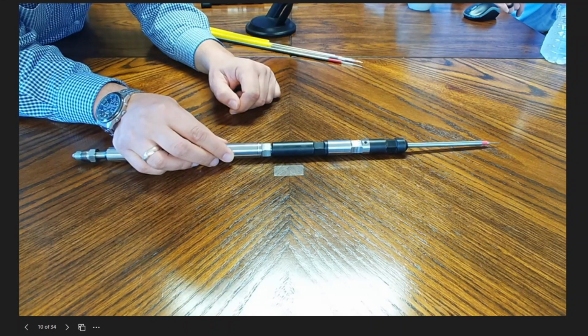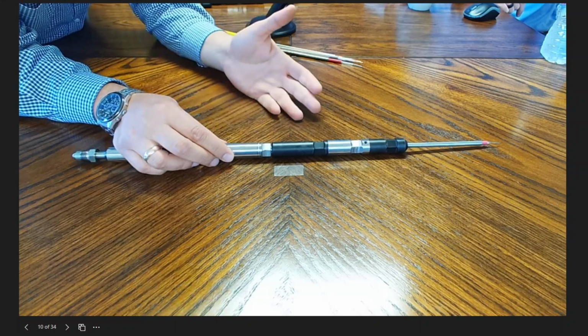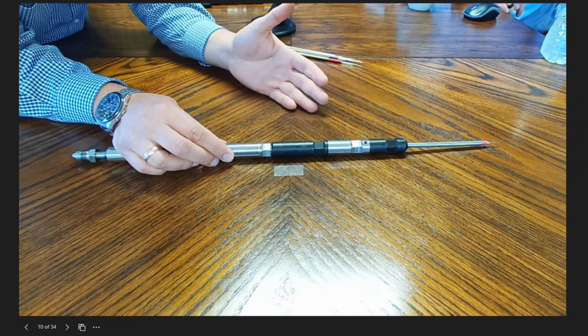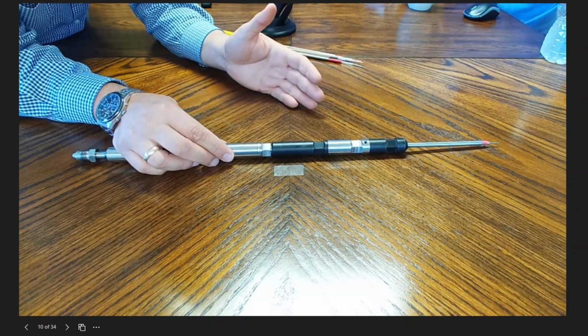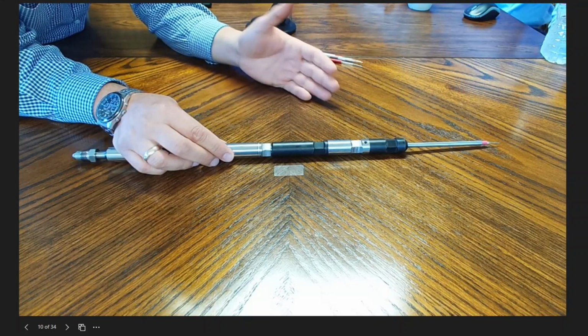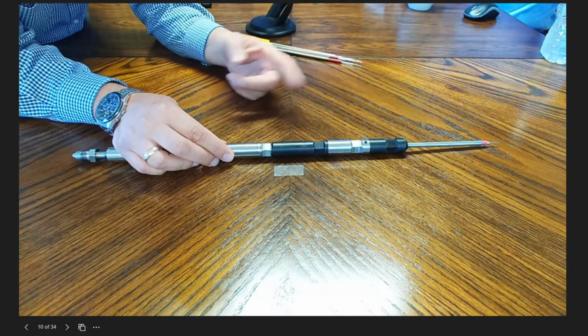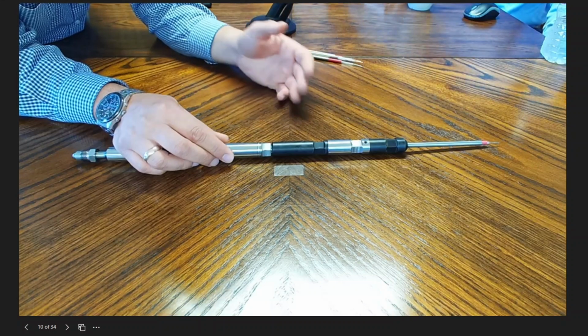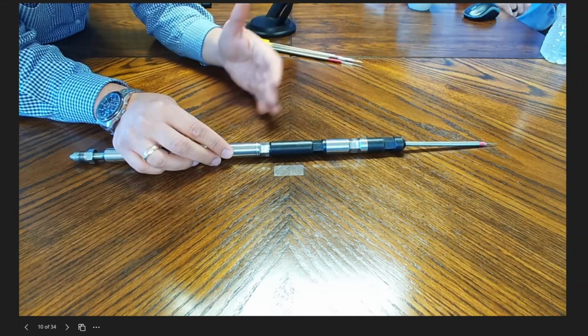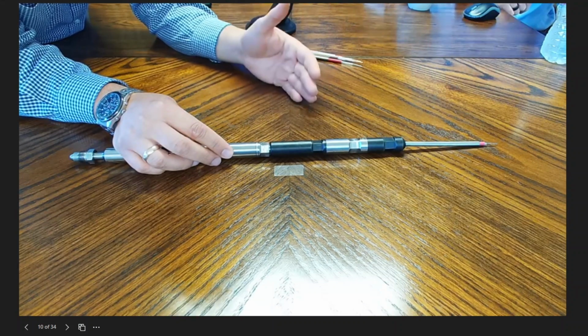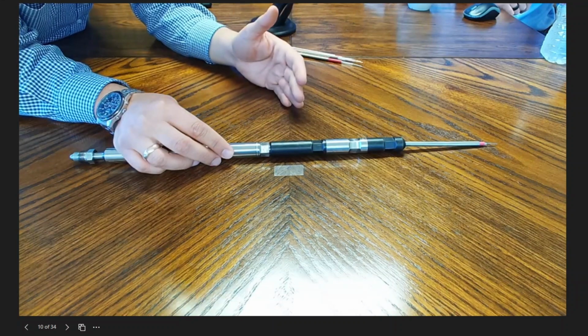We normally, pressure testing is project specific. It depends where you are going to deploy the gauge system. Normally, you want to be above the pressure where all the connections are going to be exposed. However, for our US operation, because that varies a lot, we typically pressure test to 9,000 PSI.